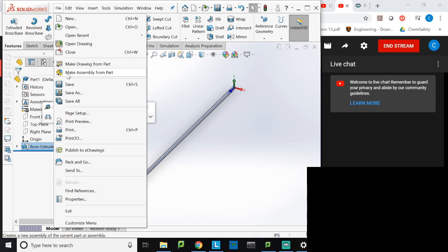It's not uncommon to have very simple parts in SolidWorks. Now I could represent this as a threaded rod. I don't have to draw it as a threaded rod. I can draw it as a very simplistic model of what I'm trying to do, and then later in the details specify this is a threaded rod, not just a solid cylinder.